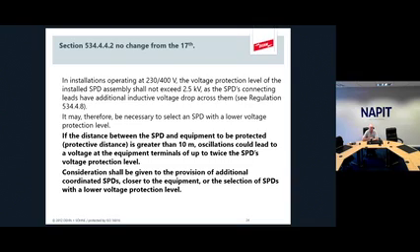And as I said before, the value of the installed SPD, including the link cables and the overcurrent protection, cannot exceed 2.5 kV. And furthermore, if I have an object, say a server rack or something else, which is greater than 10 meters away, I do need to consider further SPDs within the installation because of the rise of voltage down long cable lengths. So that's another reason why I'd need further SPDs in an installation.